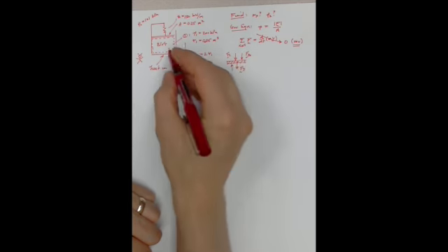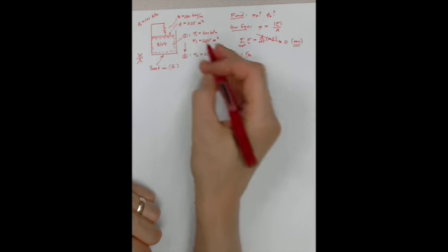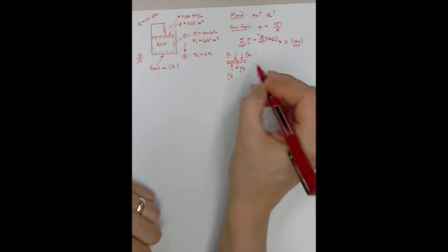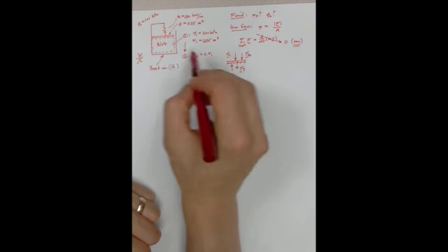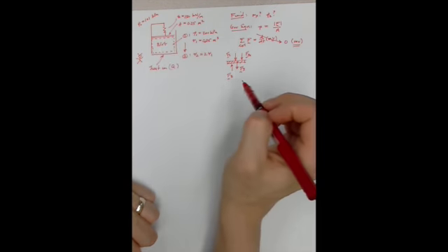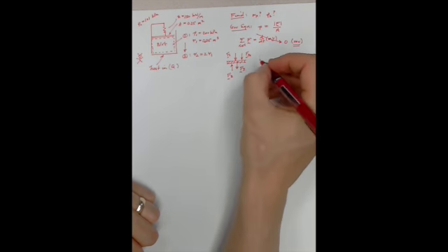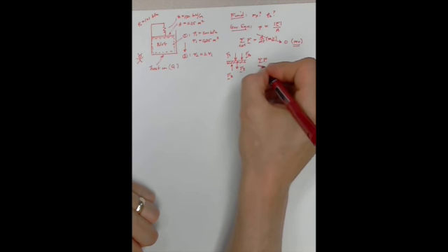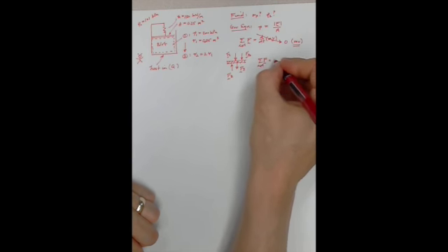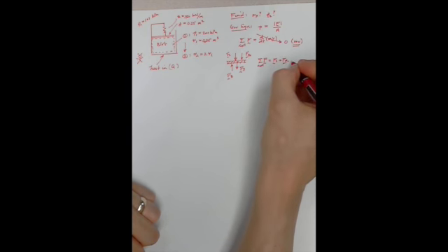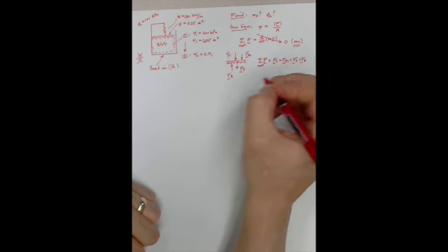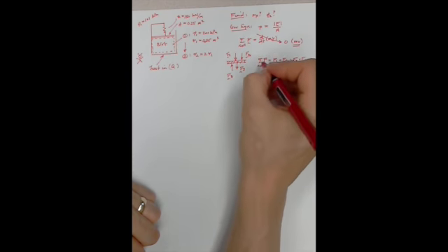And then lastly, this piston is really floating on the blob. So there's going to be the pressure due to the blob pushing up against that face, and all of those are going to be in balance. So the sum of the forces here is just the spring force, the atmospheric force, the gravitational force, and the force of the blob, and all of those are equal to 0.